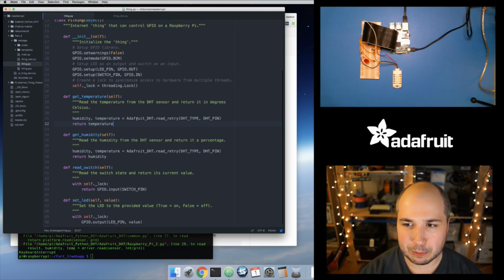Suddenly you're in this multi-threading world, and like we looked at before, you do have to think about serializing access to your hardware. So worrying about what happens if multiple things try to read the hardware at the exact same time. Are they going to overwrite each other and collide? What if the kernel lets half of one user's read retry function run, then stops it halfway through and starts the other user's read retry function? Your hardware, there's only one thing. It doesn't have any concept of multi-threading. So if halfway through sending out a reply, it gets the Pi asking it again to send the data, it's going to get confused. So again, I want to think about serializing access to this sensor and ensuring that I don't let multiple read retry calls happen at once.